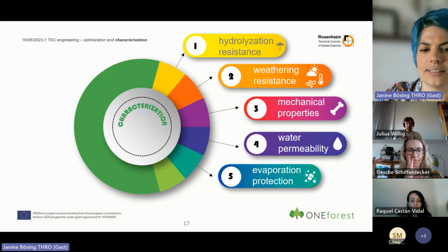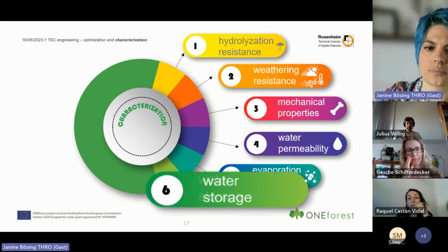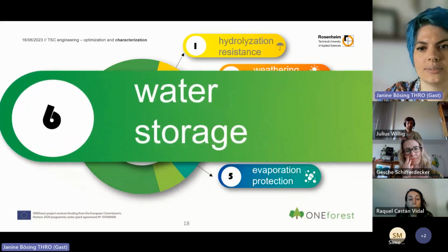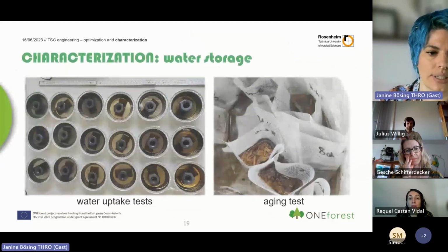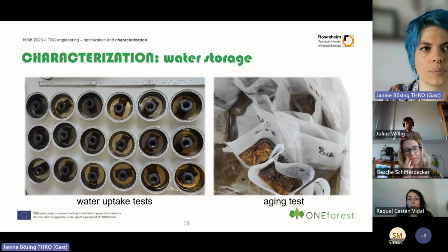And lastly, I want to talk about the water storage capabilities of our topsoil cover. For that, we are doing different tests. For one, we are doing water uptake tests, which you can see here on the left. For that, samples get stored in water for specific amounts of time. And then we measure how much water gets taken up by those samples.